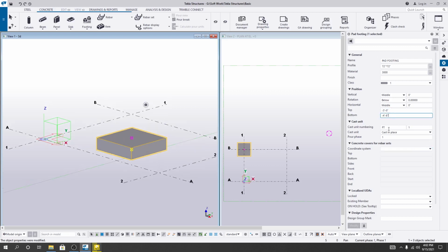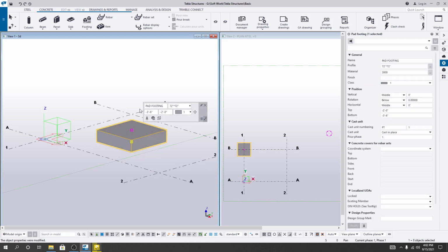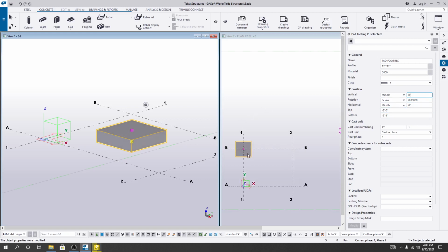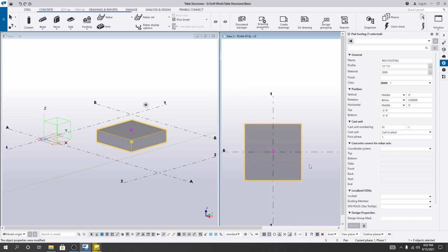So after that, also if you need to move that to the top, now here if you provide 2 feet, and also if we provide here 3 feet 6 inches, then modify, just see, it will go top. In this way you can change its foundation size or the movement of that foundation. Clear? So if you need to move that foundation in any direction, here in the vertical direction, if you need to design an eccentric foundation or footing, then you can use that option.